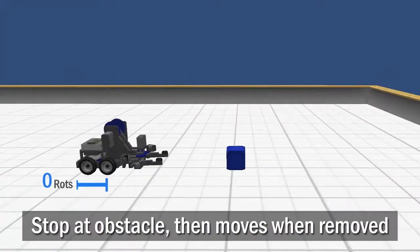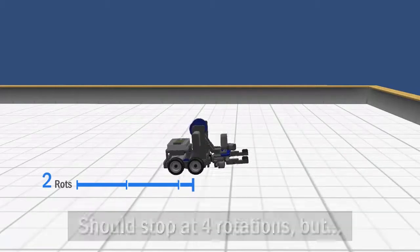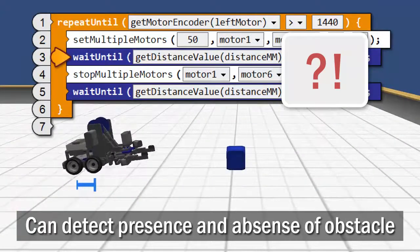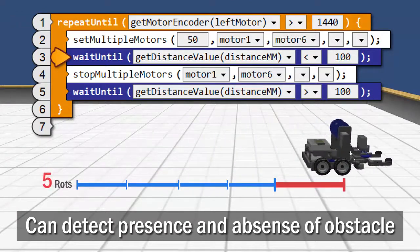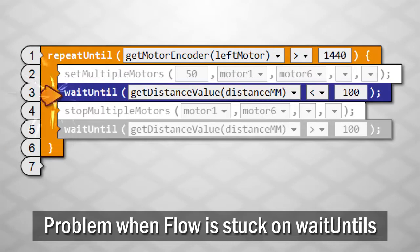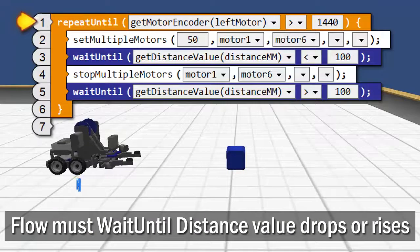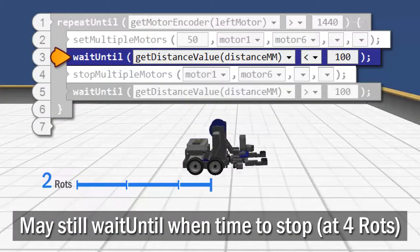The program responds to an obstacle and starts moving again when the obstacle is removed. And, well, the wait until distance behaviors can detect the object's presence and absence and let the appropriate stop-and-go behaviors run. However, because the Repeat Until loop only checks the motor encoder at the beginning of the loop, the way that the Wait Until blocks hold up the program still causes a problem. While the program is waiting for the distance sensor value to drop or rise, it can't be checking the motor encoder, and so the robot may miss its cue to stop.